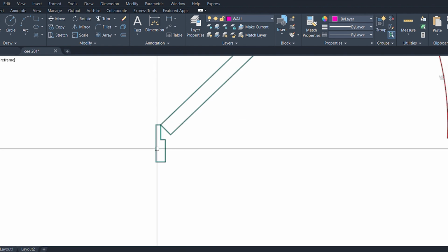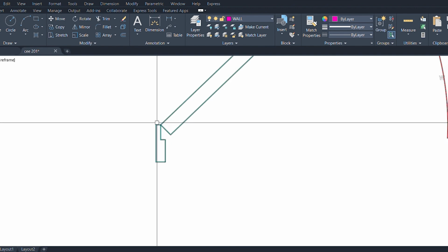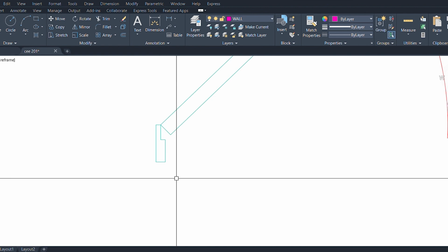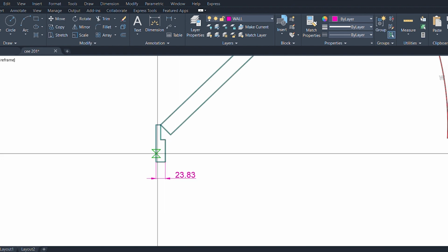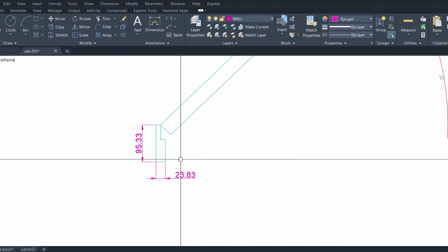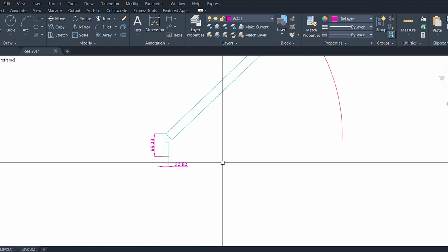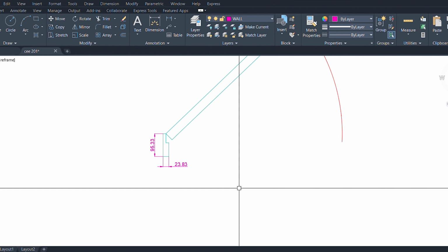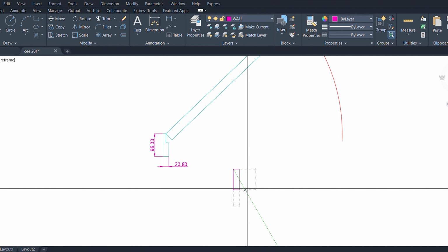So this particular part is about 100, yes, 100 by 25. Let's confirm that. Yeah, this is approximately 25. Then this place should be about 100, yes, 100 by 25. So when you want to draw yours, you're going to make that particular part 100 by 25. You can make use of the rectangle, then specify the first point, 25, 100, press enter, and there you have it.